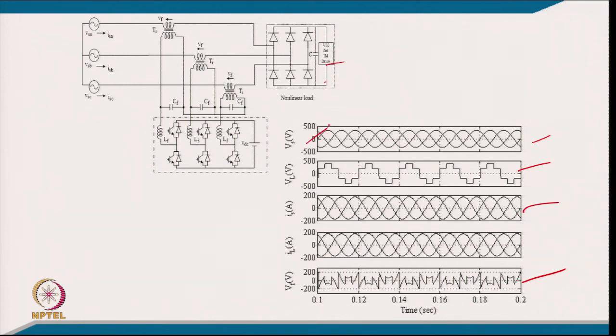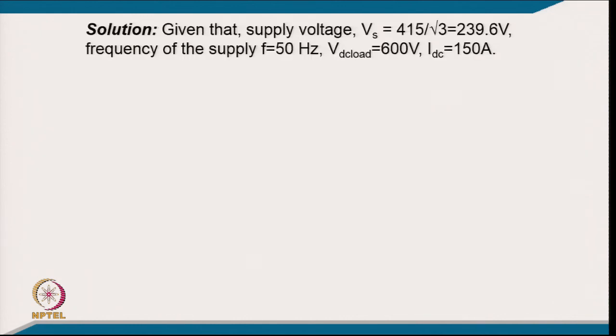So, it means on the supply we will get a sinusoidal, balanced current at unity power factor, and this is of course the PCC current, because it is in series. So, both currents will be the same. So, this series active filter is virtually working for eliminating the current harmonics, not eliminating the voltage harmonics, but we are injecting the voltage in series. So, that is why we call it the series active power filter.